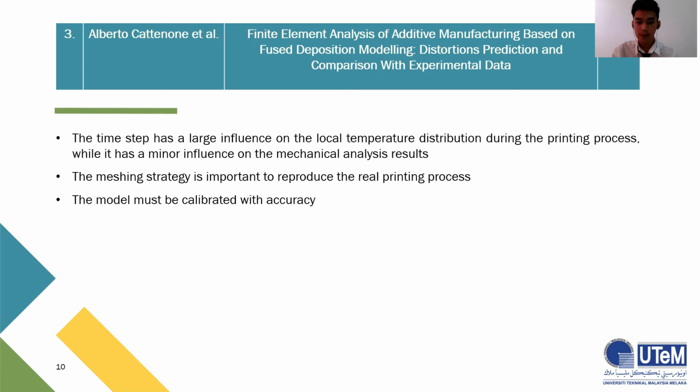Number 2, the meshing strategy from the drawing software is important to reproduce the real printing process. And finally, the model must be calibrated with accuracy because in particular, temperature dependency of Young modulus and yield stress limit must be taken into account.